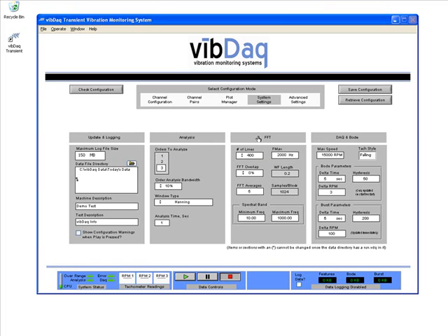Another group of settings deal with FFTs and displaying data in the frequency domain. Some of those include number of lines, averages, and max frequency to show on spectrum plots. Finally, we'll set some parameters to define how often we will write data to log files. We can specify log intervals in terms of changes in time or changes in RPM.